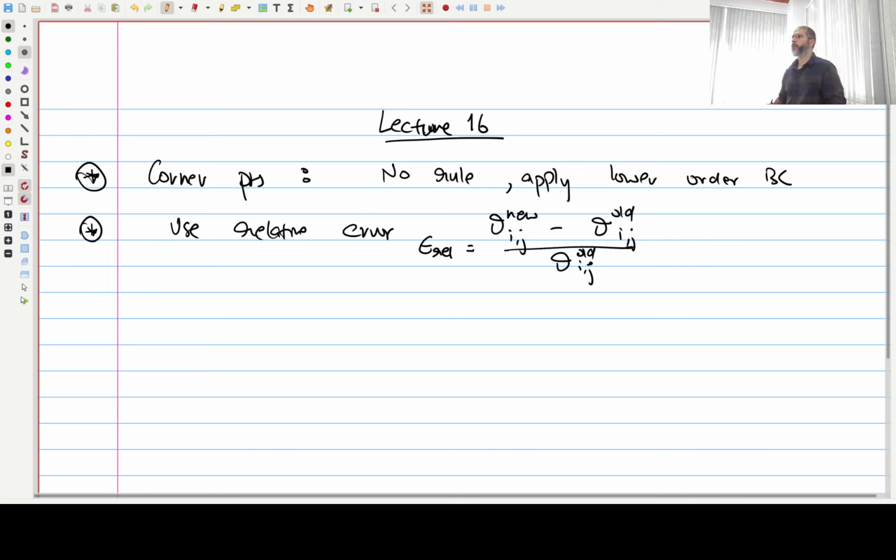And you can use this to calculate your RMS value, the L2 norm. That is much better when comparing with the tolerance than using the difference of new and old. The reason is that the theta values can have different orders in the domain.